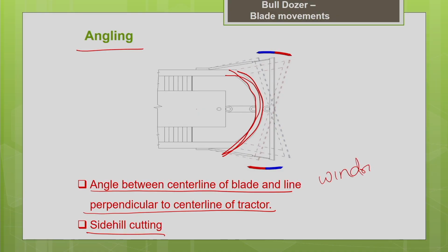So you can just strip the soil and deposit the soil in windrows. Using this angle blade, it is very easy to do. But basically angle blades are not considered highly productive blades with respect to earth moving operations. They are not very good at cutting and pushing the earth. I will discuss that in detail when we discuss the types of blades.